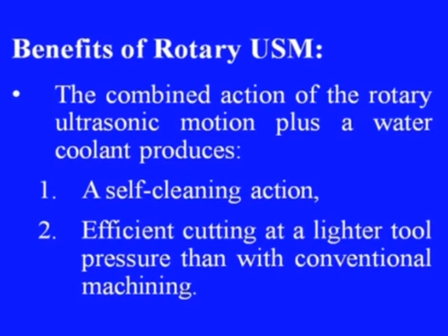Let us see the benefits of rotary USM. The combined action of the rotary ultrasonic motion plus a water coolant produces a self cleaning action. Because the tool head is rotating, it gets washed continuously, and then there is efficient cutting at a higher tool pressure than with conventional machining.